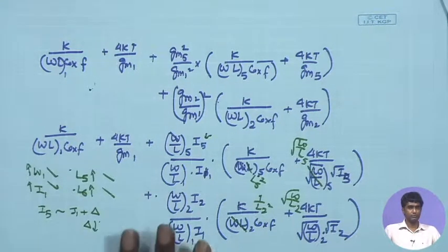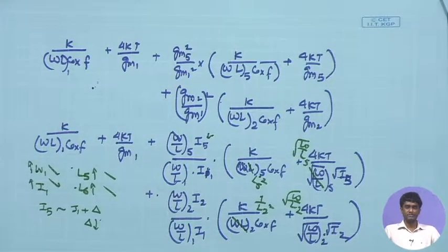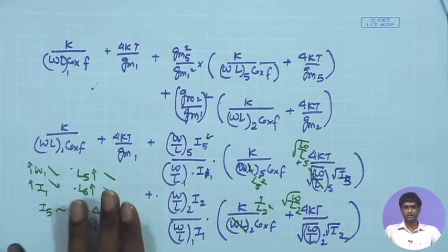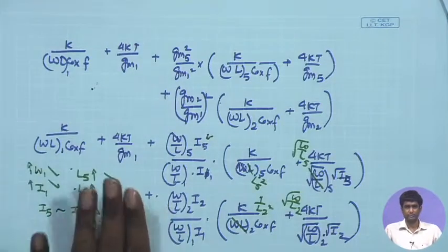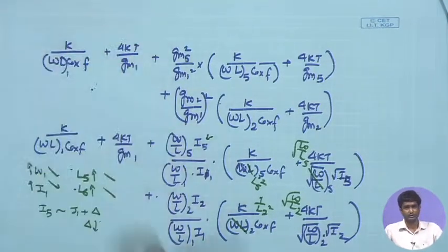So, here you have to go back and look at the constraint that we discussed with respect to stability, that is, what is happening when you are trying to compensate the loop, and which capacitance is dominating, which device is contributing. So once again, from here we can go back and check what happened to the compensation scheme that we discussed, if we go for noise minimization, whether it is conflicting with my compensation scheme and whether it is increasing the capacitance at the non-dominant pole.